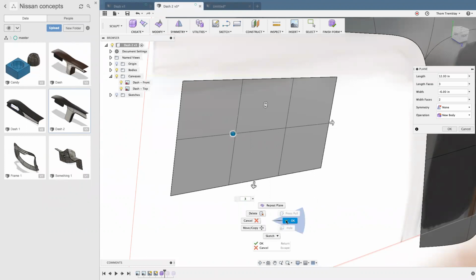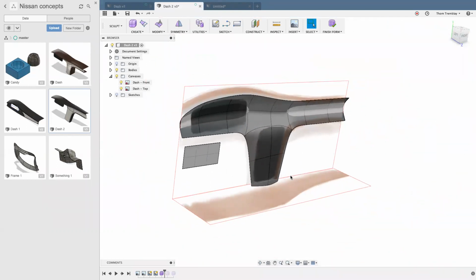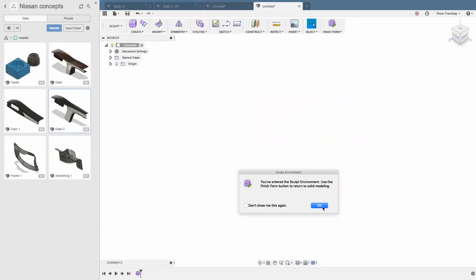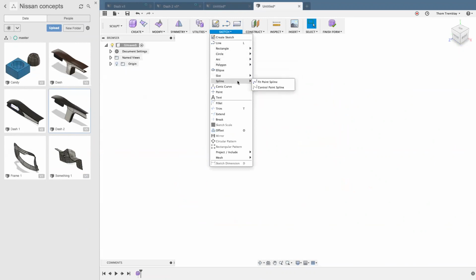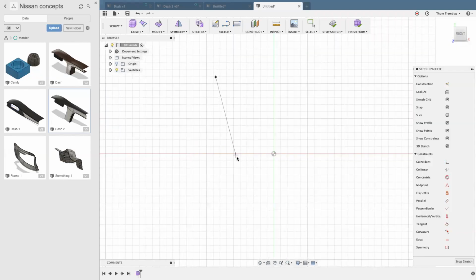Another option that we have is, well, I've been using primitives and then using edit form to make modifications. We also have the option of beginning by using either 3D primitives or also using sketches. So if I wanted to create the initial shape of maybe a seat pan, I can start a new edit form, and there are still our sketching tools. So if I wanted to, I can come down to tools like Fit Spline, select a sketching plane, and use just the plain old spline tool.